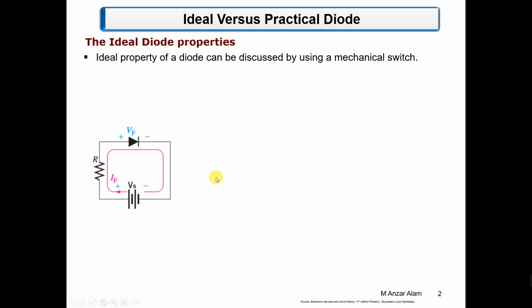So this is the resistor circuit, and we have to understand why this resistor is here. This is the important understanding, because this is the first circuit, so we will try to elaborate it more and more. Let's suppose we don't place a resistor and we make a direct connection from the battery to the diode. What will happen? The plus is directly connected to the anode, and the negative terminal of the supply is directly connected with the cathode. So immediately the supply is connected, immediately the diode will be turned on. And what is the ideal status of the turn on? It's a short circuit, so it will behave as a short circuit.